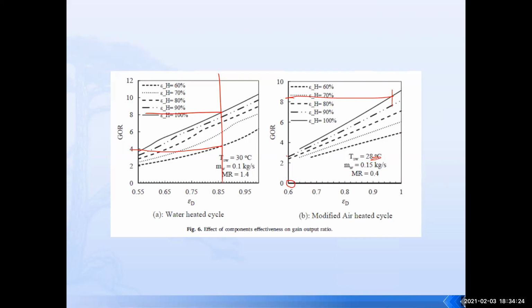And this probably is why we came up with the idea that the packed bed effectiveness is going to have some sort of a limit, and we better move to bubble column units in which there's direct contact between air and the water in the form of bubbles rising in a water stream, and that has a higher order of magnitude heat and mass transfer coefficient, and then the effectiveness of the unit is very high.